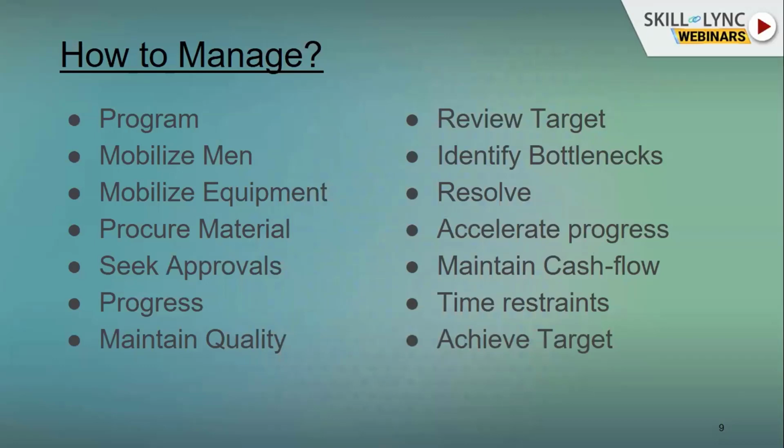But in the meantime, definitely he has to target some bottlenecks. For example, if we are doing foundation work in the monsoon, the major bottleneck is the water logging in the excavated area. So try to plan in such a way that the foundation work can be completed before the monsoon, or you start after the monsoon. Such planning gives you the experience as well as the knowledge of what kind of works to target in which season. Everything should be planned in the initial stage, so it is better to identify the bottlenecks, and accordingly we will resolve the issues.